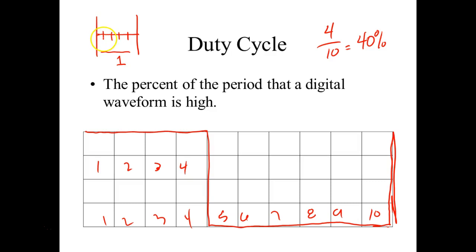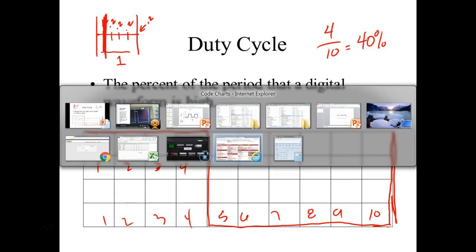If that's equal to a 1, how would I get a 1? I can't say 0.1, 0.2, 0.3, 0.4. I've got to end up with a 1. So that means each one has got to be equal to a 0.2. So if it comes over right there, then that's going to be a 0.2. You understand that? So first of all, look and see what you're counting in. If I'm counting in ones, then each minor division is going to be worth 0.2.